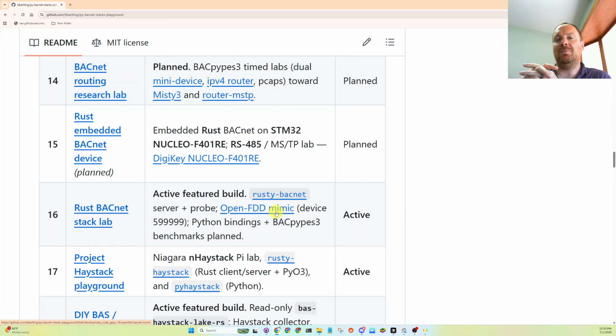And now we can give the building automation system data from the web, which can be better than local building sensors for weather. Outside air dry bulb temperature sensors in building automation are known to be flimsy, cheap, often installed very poorly, and not nearly as good quality as a local airport weather station. So one of our apps was to get that data into BACnet as a BACnet server.